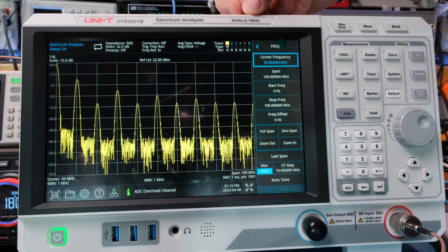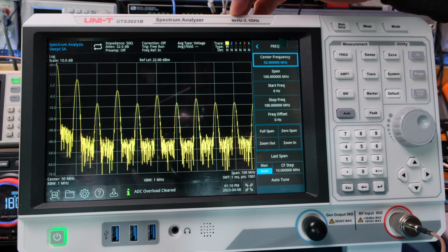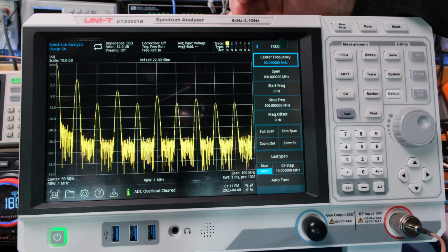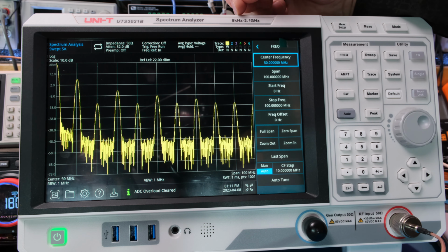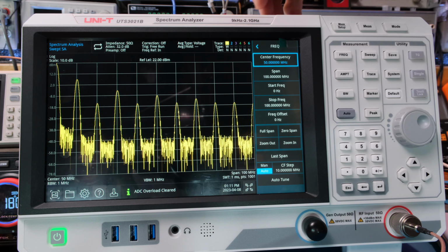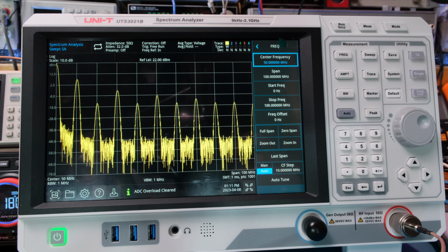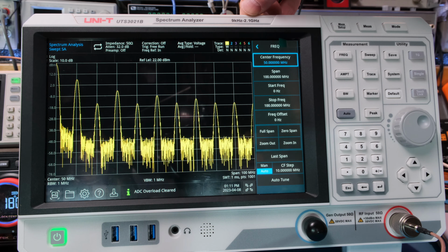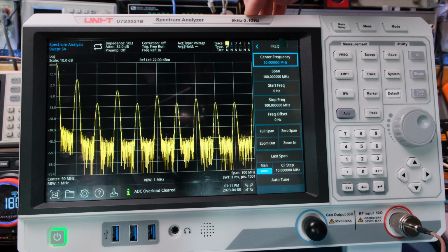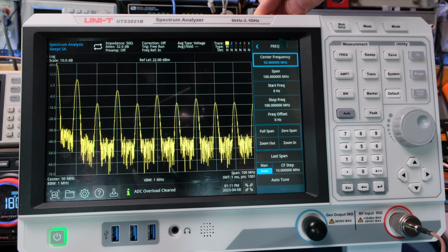Now, really, a spectrum analyzer starts at 9 kilohertz. If you guys know why they start at 9, it's funny they don't start at 10. I always wonder why they didn't start at something that sets up on the logarithmic graph. But I always just assumed it was because by 10 kilohertz you want it to be flat, so they run down to 9. And it's kind of funny, it goes to 2.1 gigahertz. Like, why not just go to 2 gigahertz or 1 gigahertz for that matter? But going to that extra gigahertz is meaningful, and I guess that 0.1 was important too. And that's the other difference between a spectrum analyzer and your FFT, is you can go way out to these gigahertz frequencies, okay?